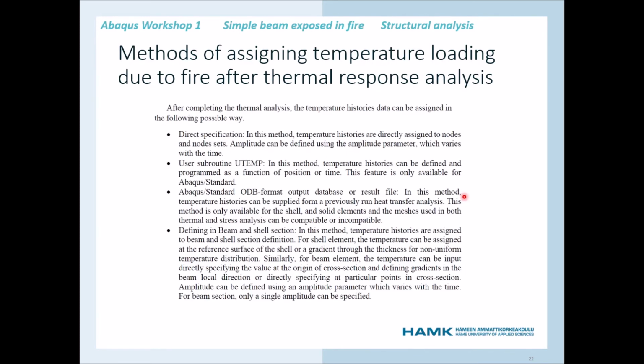And in Abaqus, the method for defining the temperature loading after thermal response analysis, we have several methods, and one of the methods is defining in beam and shell sections. So in this method, temperature histories are assigned to beam and shell section definitions. And for shell, the temperatures can be assigned as the reference surface of the shell or gradient through the thickness for non-uniform temperature distributions.